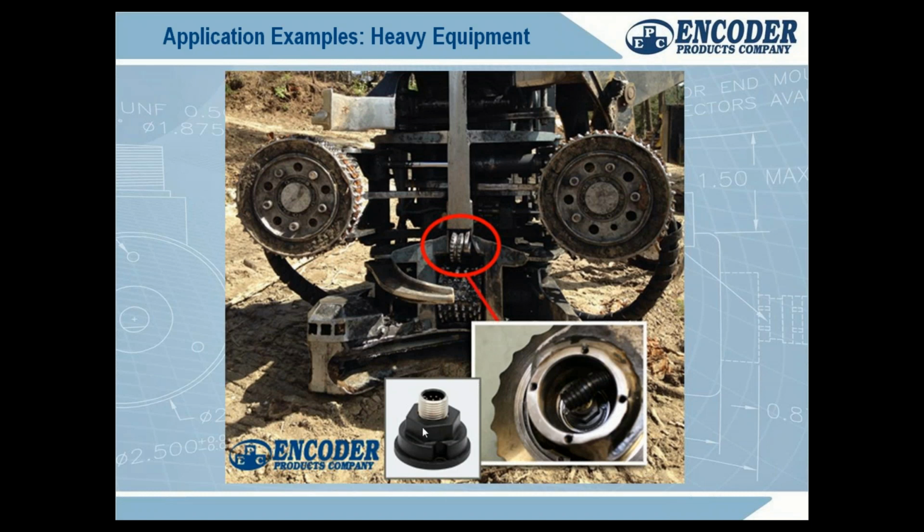Well, our little magnetic encoder here is installed in this wheel. So when the logging truck pulls up, they turn this sideways, and the operator just hits a footage: 8 foot, 10 foot, 12 foot. And once he hits that, this is all automated, and it's exactly the same length every time because they're measuring the linear distance of that log with an encoder inside this wheel.